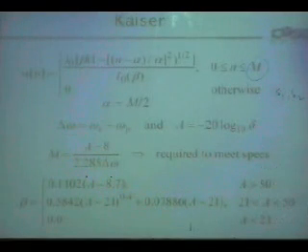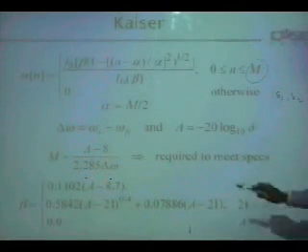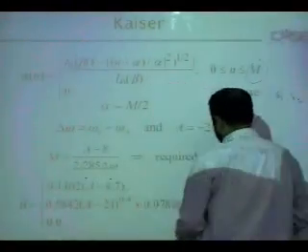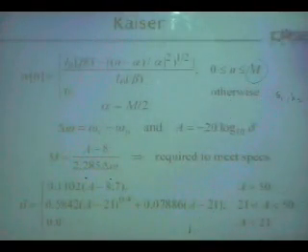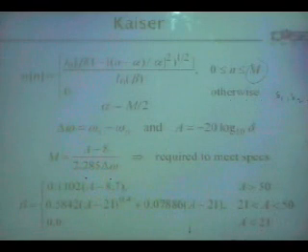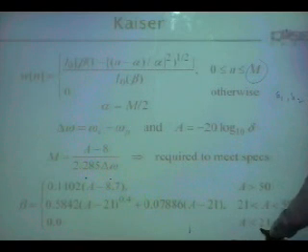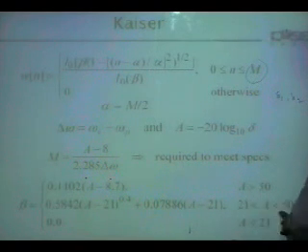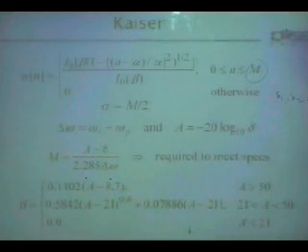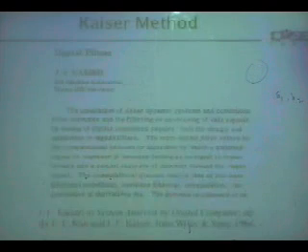Say, you want this much rejection and this much suppression. I'll say this length will be enough. So this is m, and then use these empirical formulas. Again, no mathematical reasoning, it's empirical. And so Kaiser came up with either the beta, I'll show you how beta affects the window shape. It says beta will be 0 if A is less than 21. If it is between 21 and 50, you use this formula. If it is greater than 50, you always use this formula. So these are the effects of betas.